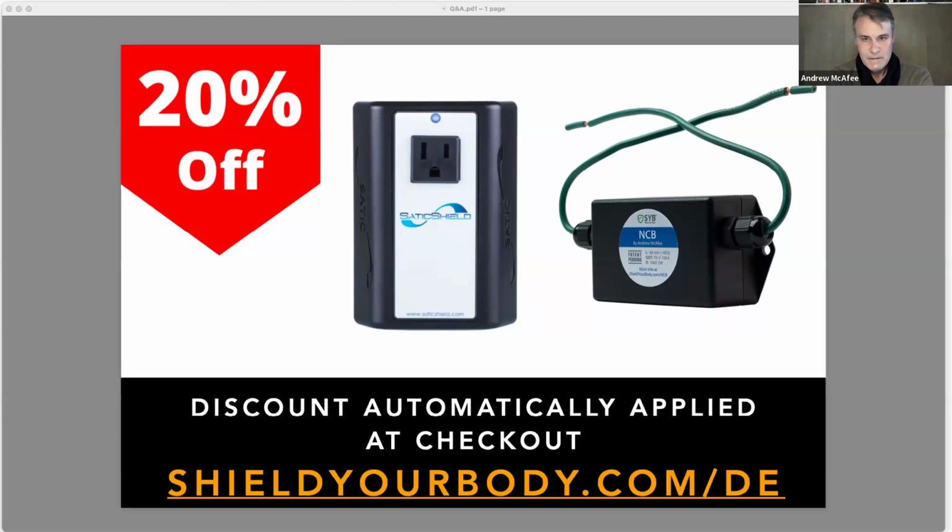Yeah, obviously the question is coming from somebody who knows what they're talking about. Now, the code says if it's under 50 volts, it's not required to be grounded. So the low voltage side of the transformer is no more than 24 volts. So that's under 50 volts, so it's not required to be grounded. Some transformers literally have one of the current carrying conductors tied to the metal frame. So I'm finding an amp of current on a coolant line, an amp of current on the grounding system coming from the furnace. Obviously, this is a health threat.